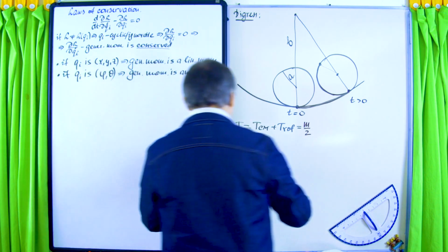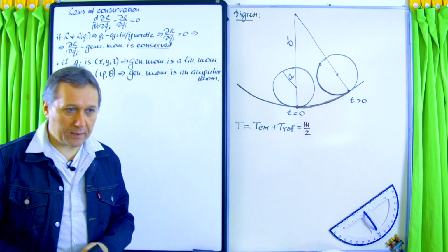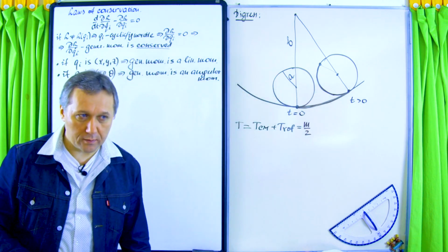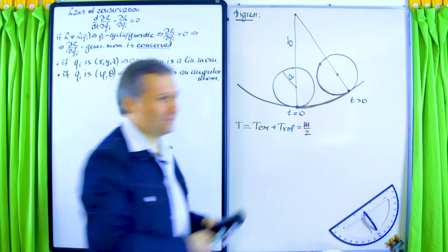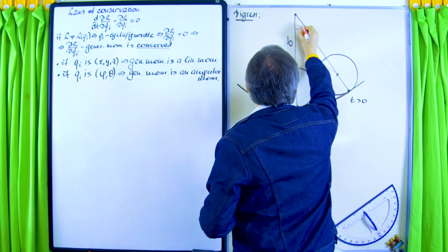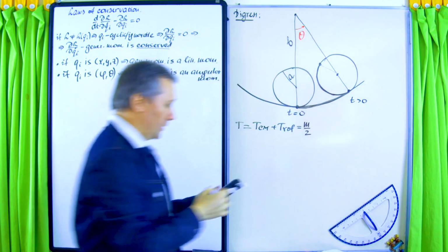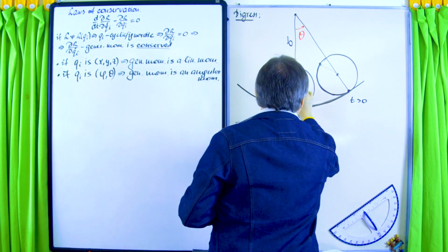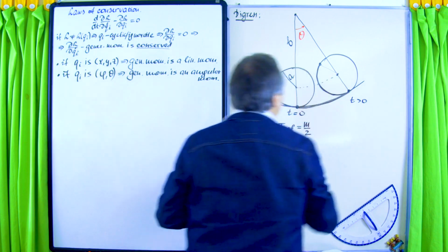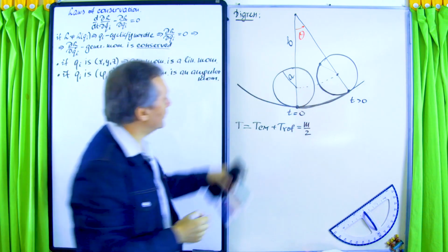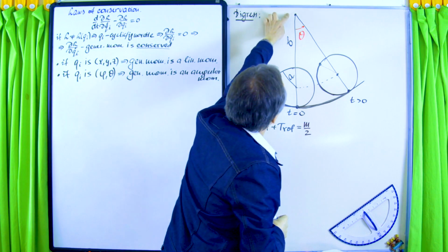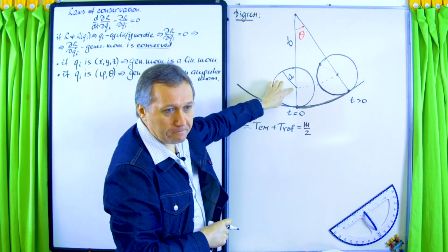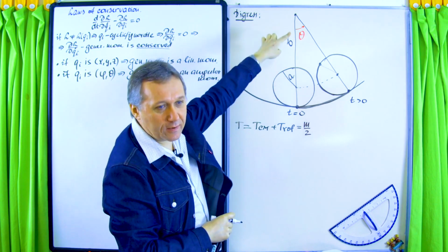And then, of course, we will have to introduce the first angle, angle theta, which will define the position of the center of mass of this, let me call it disk. So let me introduce this angle theta. Using that angle, this is the trajectory of the center of mass, and this distance will be b minus a. So it will be m over 2 times (b minus a) squared times theta dot squared.